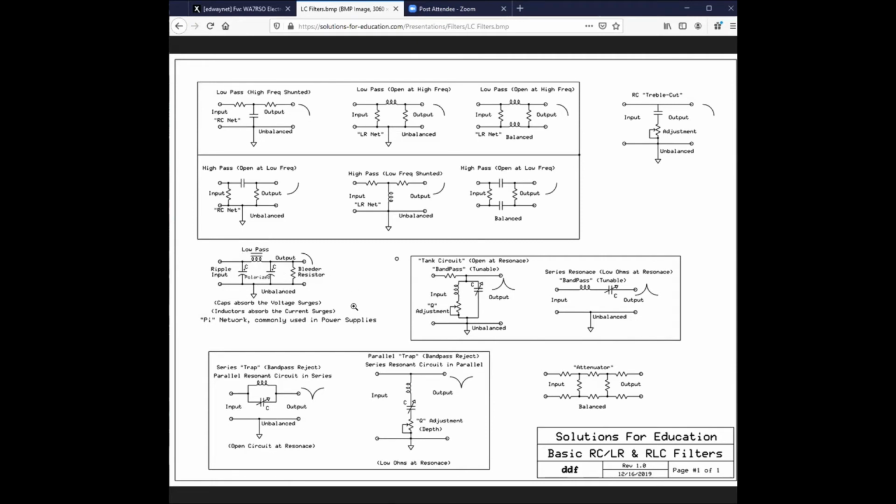However, something else that you do, if you ever build a power supply, you have to put a bleeder resistor in there, because if you turn the power supply off, these will remain charged unless you've got a load sitting out here. If you don't have a load, you can have a very dangerous situation. Back in the days when I built a power supply for tube radios, this was like 450 volts here, not something you want to put your fingers on. So if you turn the power supply off, you want it to, shall we say, bleed down so it becomes safe.